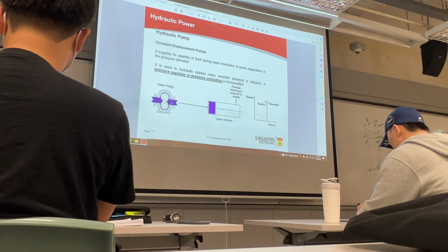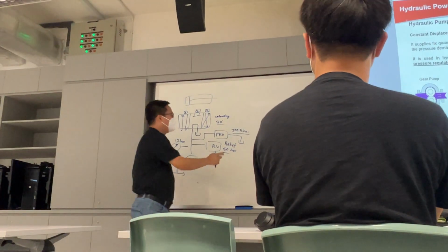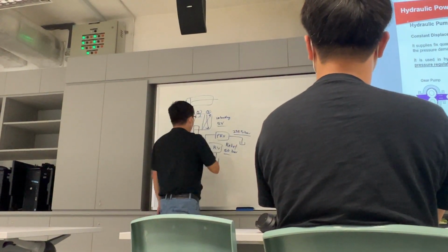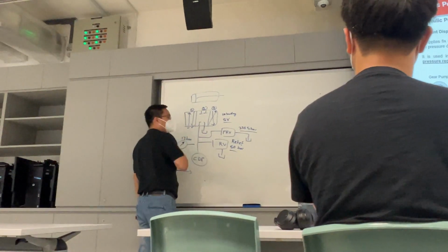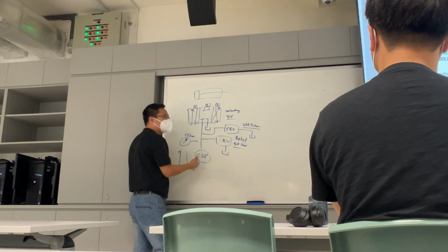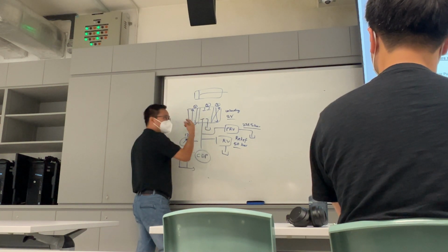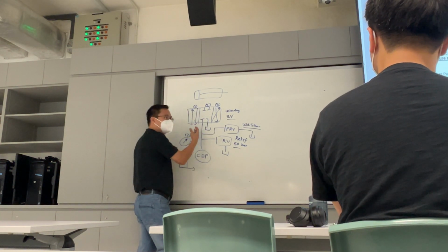This one is the same as your back valve, your output valve. It will regulate the pressure for you. Now, if I say this is a closed center selector valve, the moment you switch on the pump, where does the fluid go? What will happen to resistance? Maximum, right? So you must relieve the pressure, right?